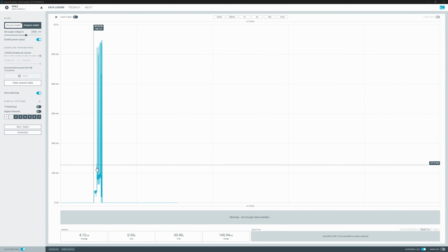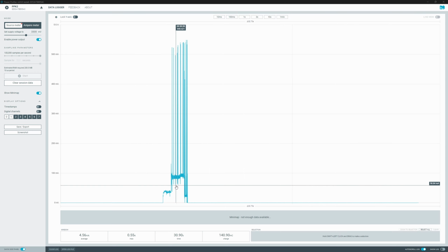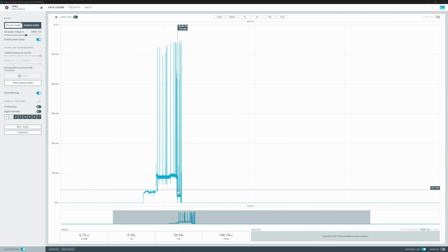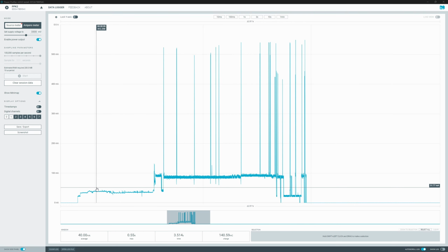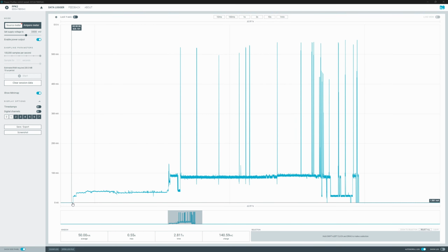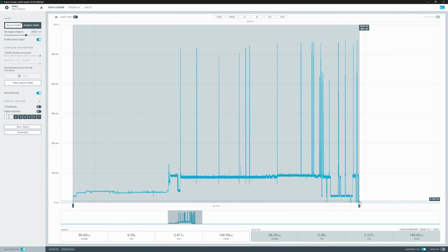Okay, let's have a closer look at the deep sleep report in the power profiler again. Zooming in on our wake up period here. So waking up, connecting to Wi-Fi, sending the data via MQTT and going back to sleep again took around 2.12 seconds. That will be interesting to compare to the other sleep method.